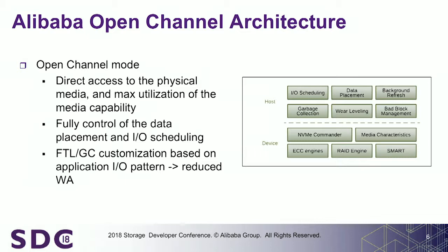They know their NAND medium better than us. So we just want the device to give us information to say, this media is at risk. You need to do something to handle it. And then the host will initialize the handling. If you are familiar with the SSD FTL, the handling usually just means you probably need to refresh the data, right? And also do some bad block management there. So those will be controlled by the host, but the monitoring will still be controlled by the device.